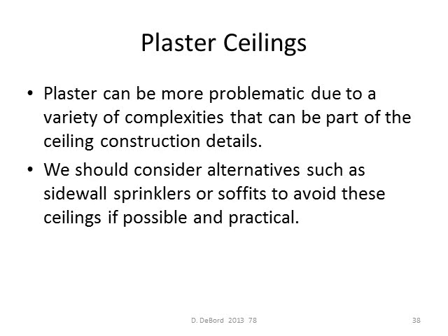It could be these arched ceramic tiles that could be 9 inches deep, and while there are holes, channels through them, they have a structural function, and you would probably have to have exposed sprinklers and piping if the building was of a historic nature and you couldn't damage the tiles.